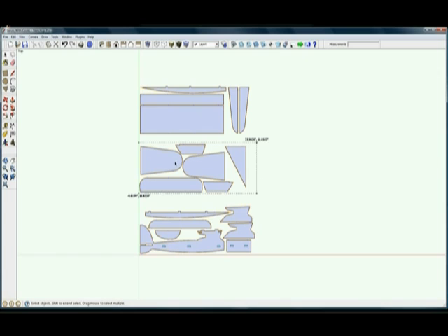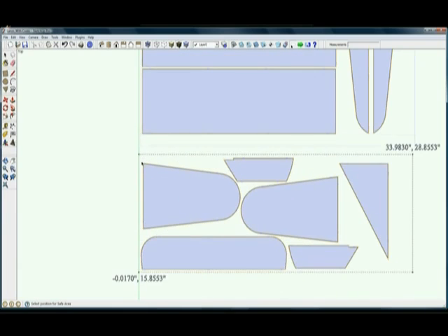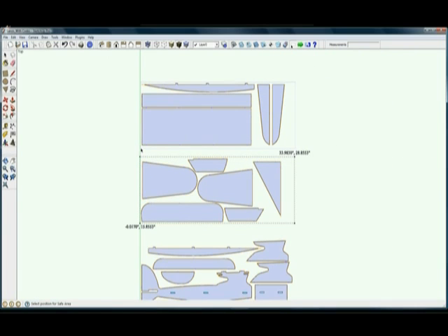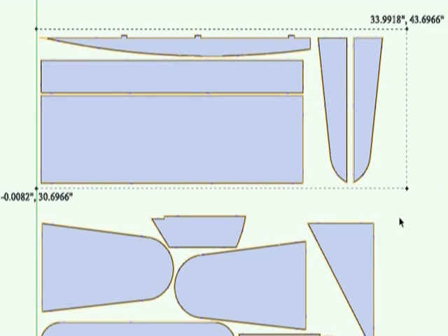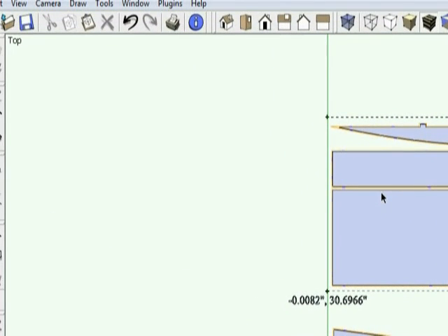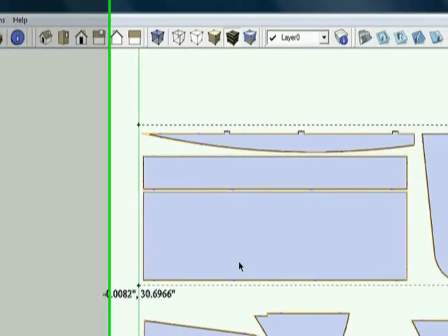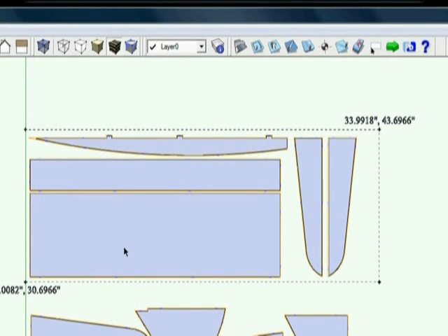So then I might generate flat code, Lanzo Bomber flat code sheet 2. And then I could do that same thing again by clicking on this button and doing the same thing for this sheet. I zoomed in too tight. And bring it into position. Click. Now when I generate my code, it's only going to consider these parts within the bounding box. So it's just another neat feature of the PhlatScript.